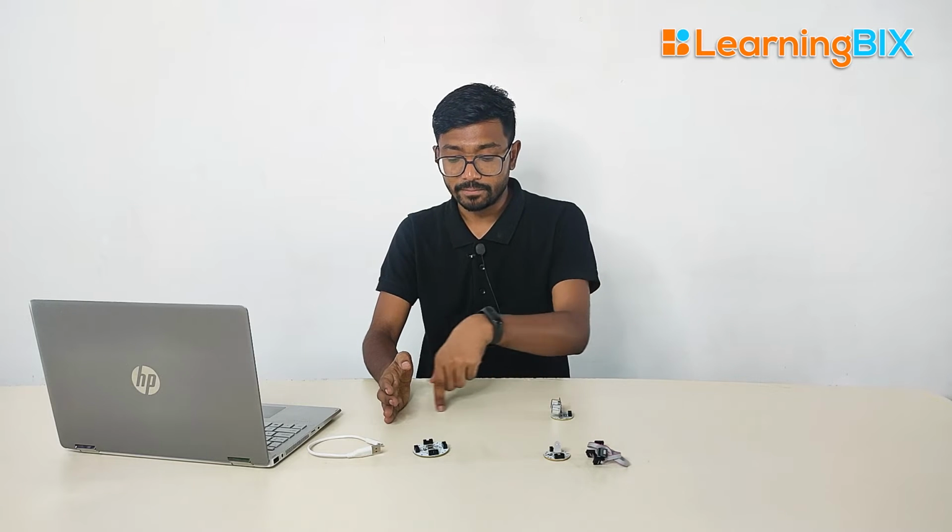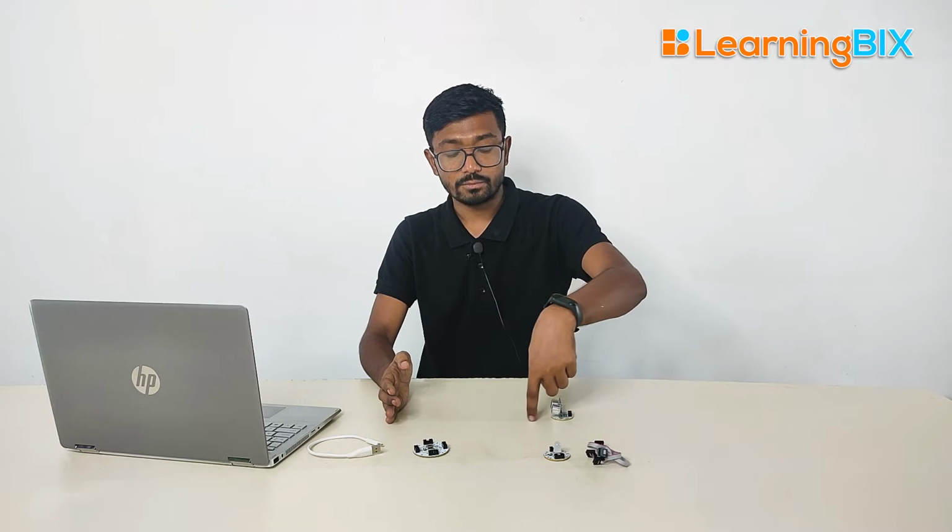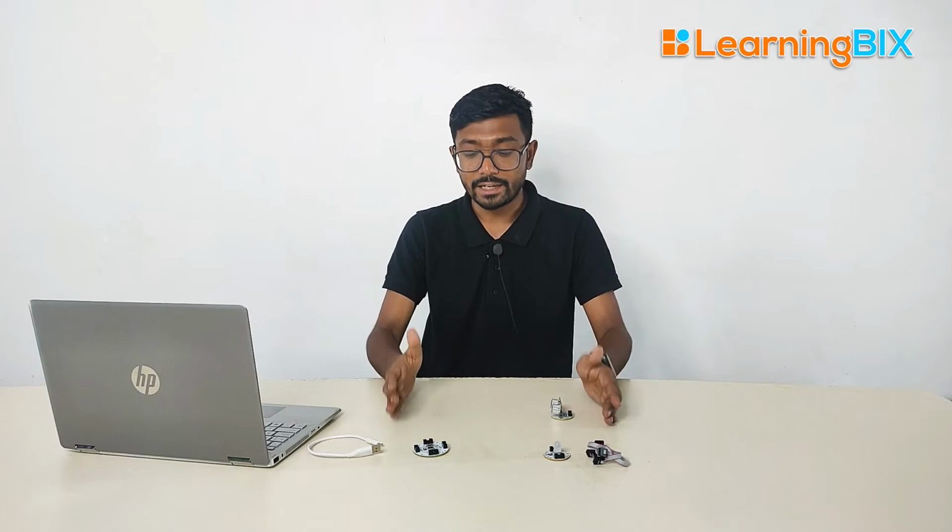Now let's assume that from here we are transmitting the ultrasonic waves, and this is an object which is placed at a certain distance. We know the speed of it. From here the ultrasonic wave is transmitted, and it is struck back by this object and received by this receiver. The time taken here is twice, going from A to B and from B to A. So what we can do is divide the whole thing by 2 so that we get the exact value, that is from A to B.